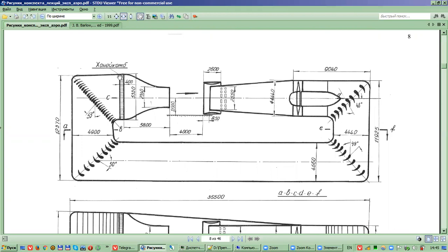And the next part of the wind tunnel is a honeycomb. This is like a bee honeycomb, yes, a lot of hexagons, and the size of these hexagons is selected to break down small vortices. So the honeycomb reduces the turbulence level in the wind tunnel. There are also recommendations for sizing of honeycombs, and this depends on flow speed and on turbulence level.